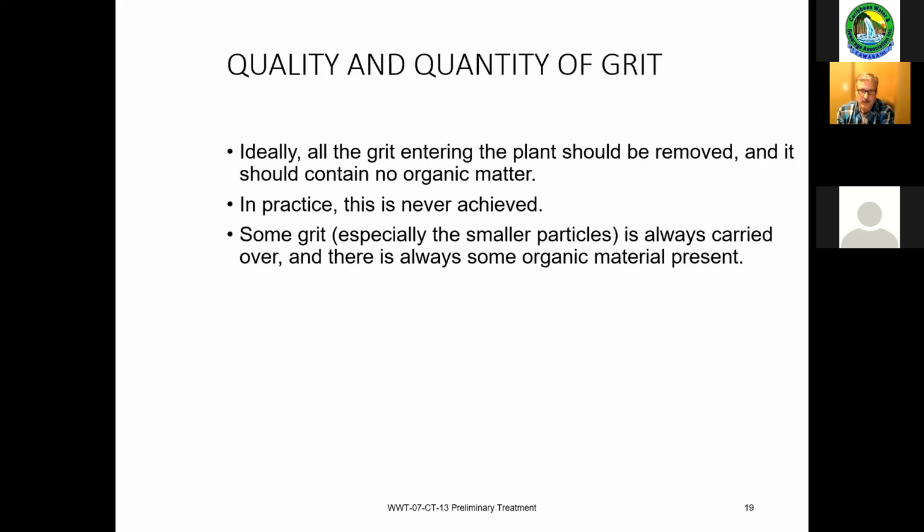Typically, a landfill will accept washed grit and screenings because they're classified as non-biological because they've been cleaned. In practice, you never achieve 100% cleaning, but the concept is that you send it through some kind of cleaning system so that it can be handled at the landfill.